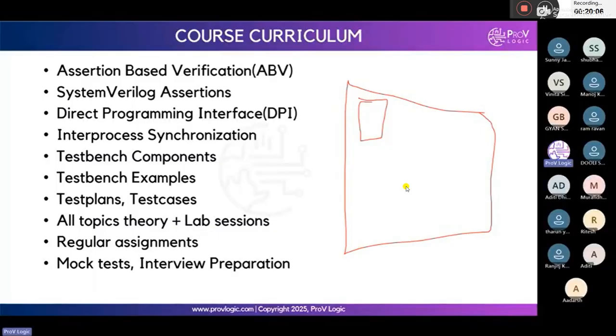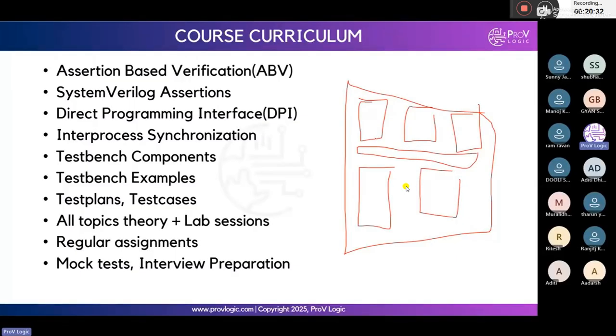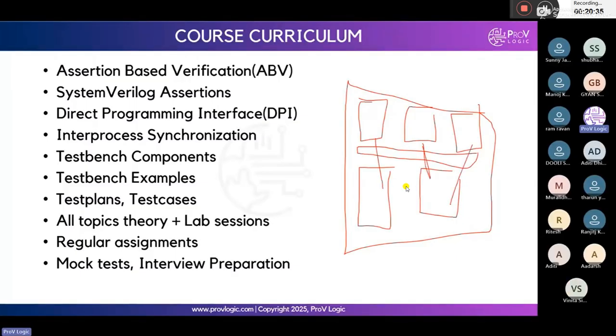I already discussed the system on chip design. What are the different functional blocks available in an SoC? There will be n number of cores, processors, graphic processor, digital signal processor, memory blocks, IO peripherals, Bluetooth, Wi-Fi module, GSM module, keyboard. There are a lot of interconnects also. These blocks will be connected through interconnects. This is the overall system on chip design, which means the whole architecture is placed in one chip. So you need to verify this whole system on chip.